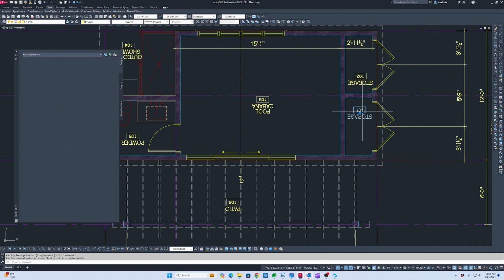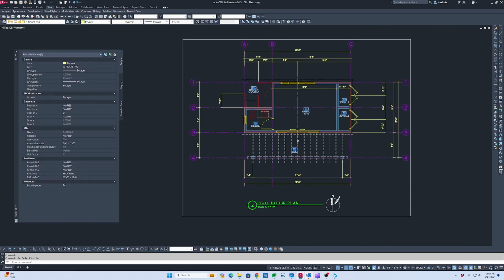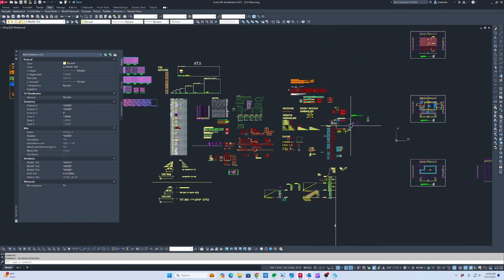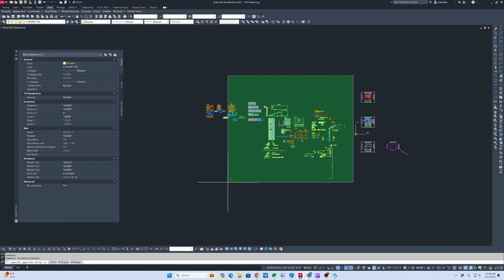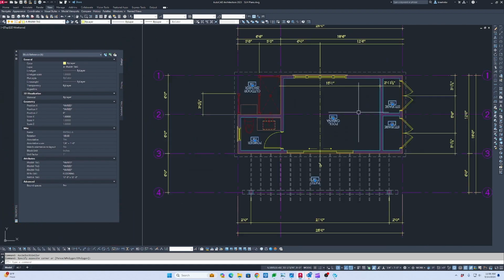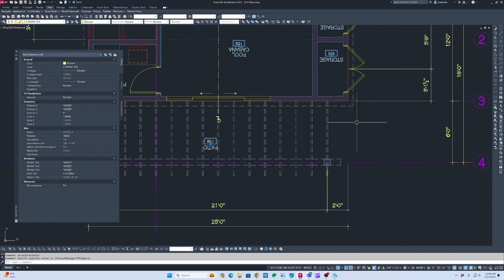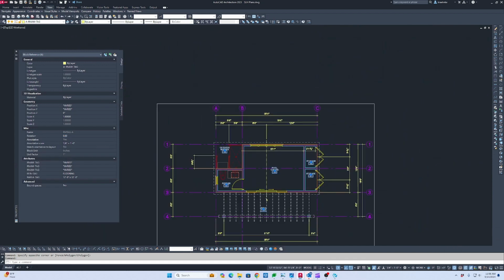So tags. Again, let's select similar. That selects everything in the drawing, because I got my template, see it selected that guy too. So everything in my template I don't want to flip, so I'm going to hold shift and deselect all of those. The only thing that's left are the ones that I care about. And because those are groups, I can change that back to 0. They should all flip around throughout the whole thing.